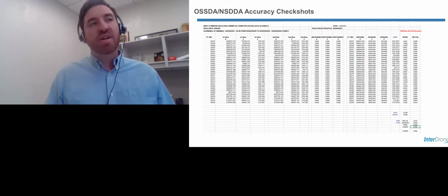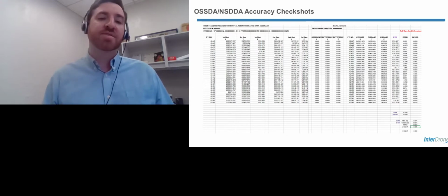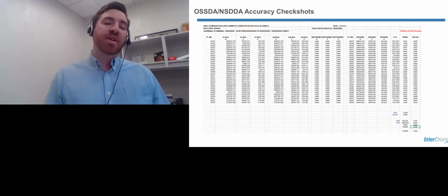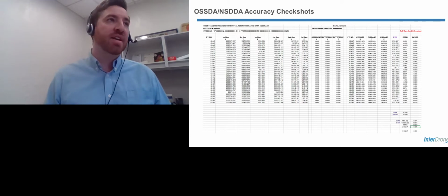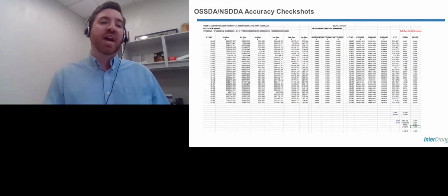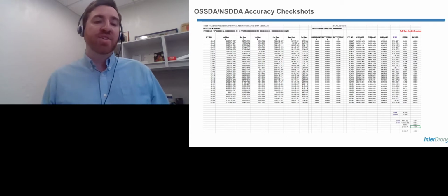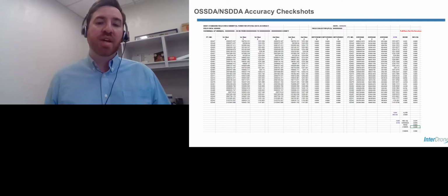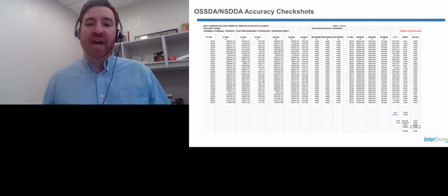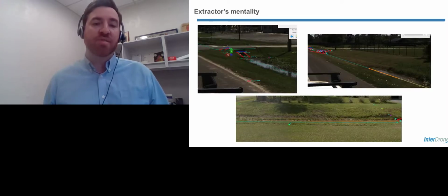out and shoot say 20 different shots across a project, and they'll bring those points back into us. They're not necessarily control points. They're just kind of random, let's call it, points. And at the end of the project, when we build a triangle file, which I'll show you here momentarily, there we are evaluating the vertical error against that surface model to see the quality of that surface.